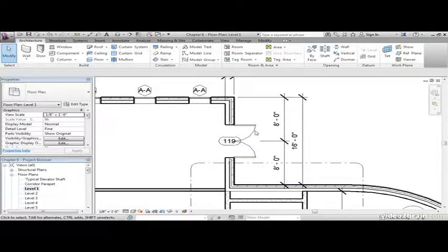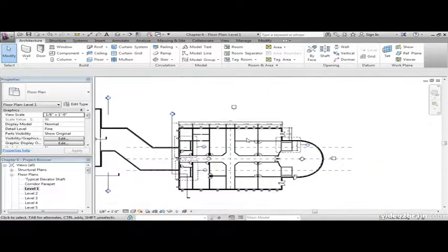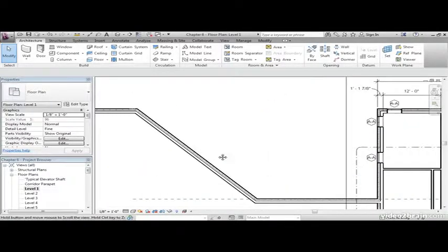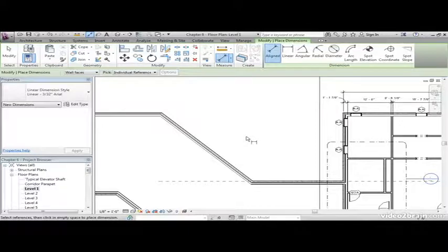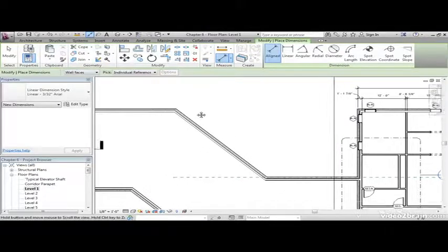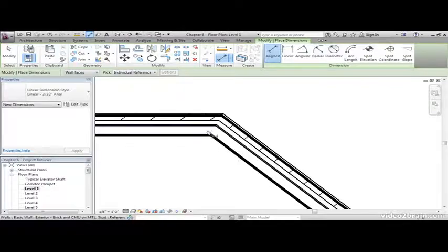Now let's move on to some harder dimensions. Over in here. I'll fully admit Revit's not the best for angled dimensions, but it's going to work out just fine, trust me. Okay, we want a dimension to come off this wall in this direction. Not the easiest thing to do. There's a lot of tabbing involved. Here's what you have to do. Zoom into the intersection.